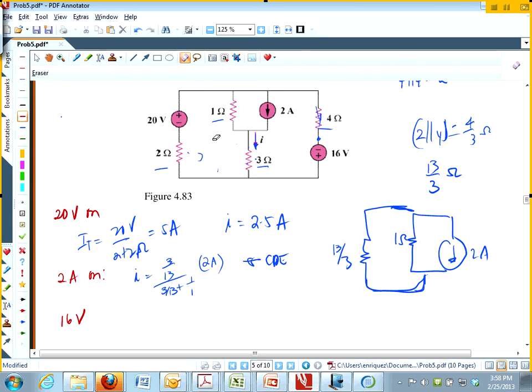So, sorry, that 4 ohm resistor all the way on the right. This one parallel to 2 all the way on the left. Correct. That's why we get the 4/3, because we shorted the 2 voltage sources. We replaced the voltage sources with wires. How's that? Smart, huh?